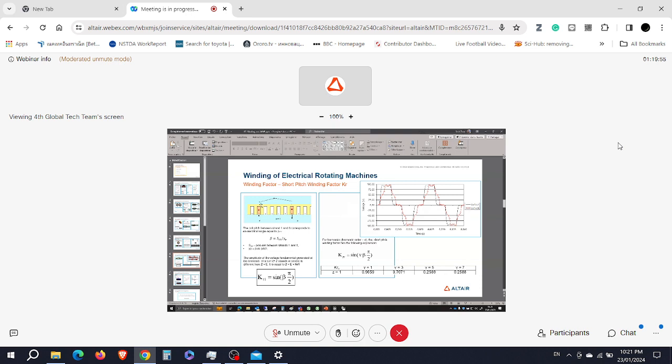So once again, we have a pole pitch computed previously. Then we can make it one slot shorter, and this one slot shorter allows us, as we can see here in red, to have a better MMF. So it's better than this full square one, because this will allow us to reduce the harmonics.